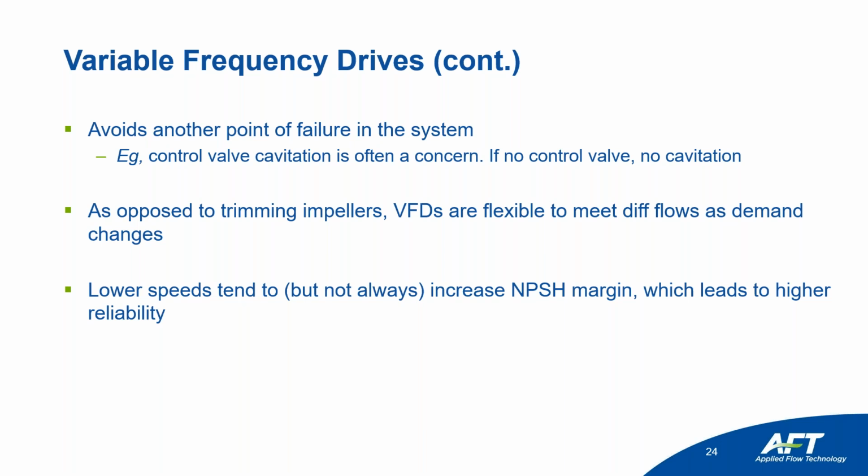That is not always true. It depends on the system, and NPSH doesn't follow the affinity laws like the others. It's totally experimental. There's no theory really. You can assume different things, like it follows some similar things as flow, where it's a function of the ratio squared. That's the way it works for head. Anyway, it just doesn't have its own thing with affinity laws. So it really depends on the magnitude. You have to do your own analysis, but typically that's a rule.